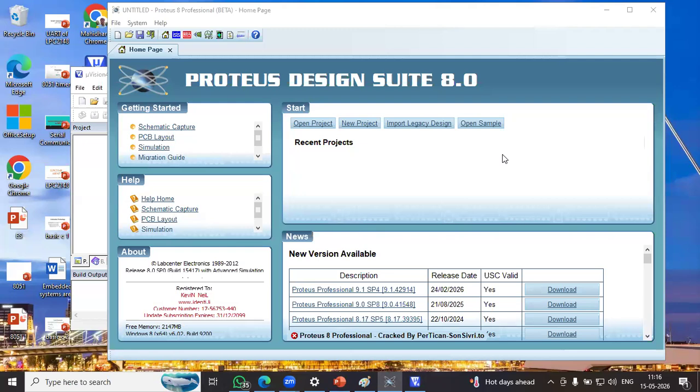One more thing, guys. First, you find out how to rectify the drawback. What is the drawback? The required voltage is 2 volts, but the microcontroller's output voltage is 5 volts. So to protect the LED, you must add a resistor, right? Yes or no, guys? Guys, please respond. To protect the LED from the microcontroller, you must add the resistor.